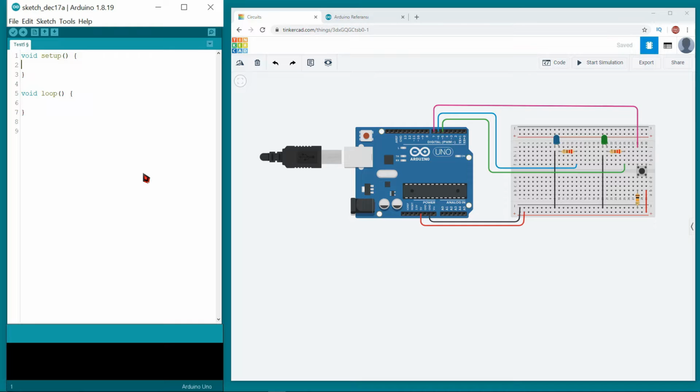If you are going to control a circuit with commands, pin definitions should be made with commands first. Similar to many programming languages, it is important to pay attention to case sensitivity when writing commands in Arduino. Otherwise, our commands may result in errors. In the pinMode command, p is written in lowercase and M is written in uppercase. We write the expression pinMode with an uppercase M for mode. Then, we open and close parentheses. To indicate the end of a line, all our command lines must finish with a semicolon.